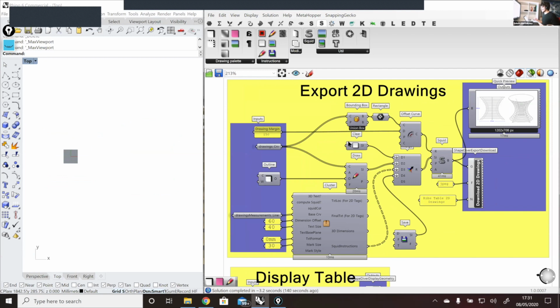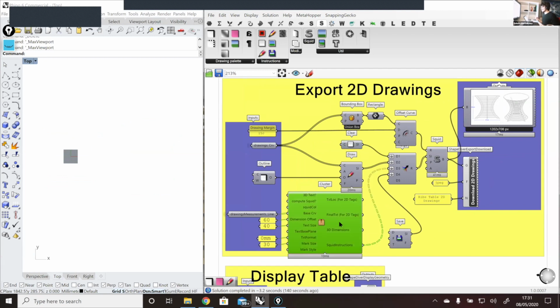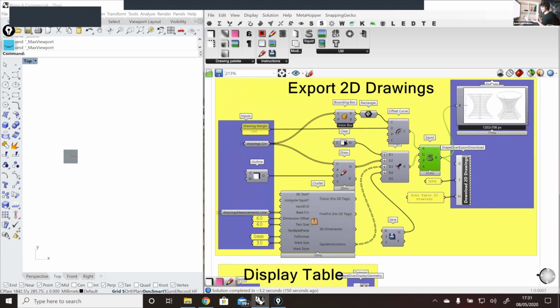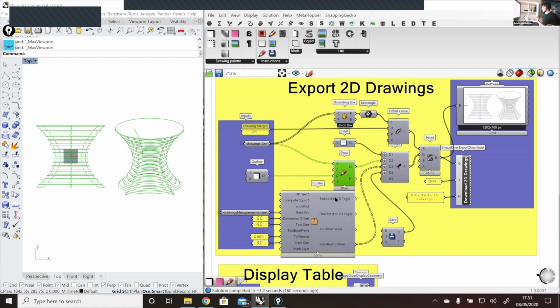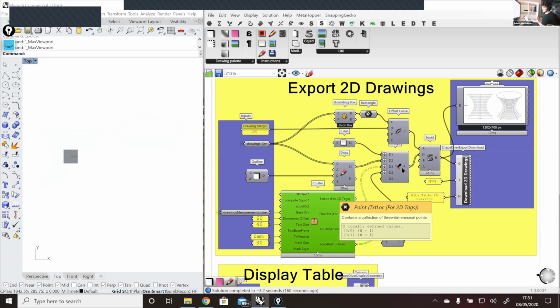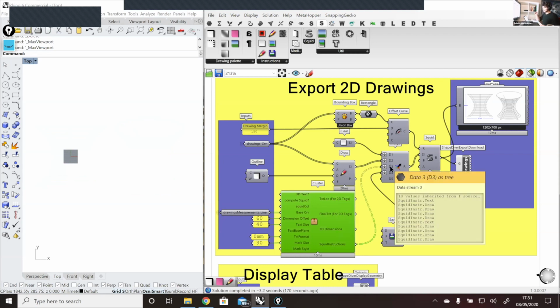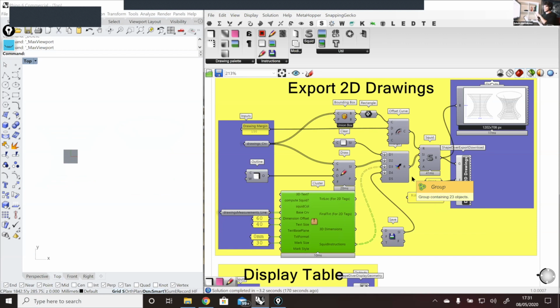Here we have other instructions, like creating some dimensions. So here first we clear our bitmap. Clear means that we paint everything in white. Then we draw our curves. So we draw all of these curves in our bitmap, and finally we create the dimensions. The same order that you have here is the same order in which everything will be painted one over the other. So you have to be careful with the order of your list here.